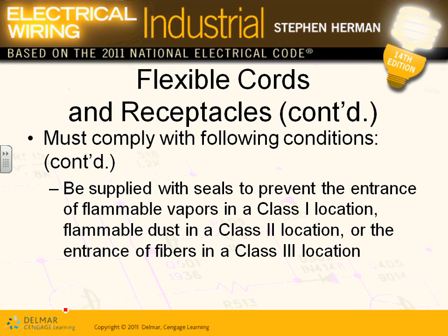Another thing, guys, for the cord: you have to have a seal in your cord to prevent the entrance of flammable gases in a Class 1 location, flammable dust in a Class 2 location, and entrance of the fibers in a Class 3 location. You have to provide a seal also with the cord.